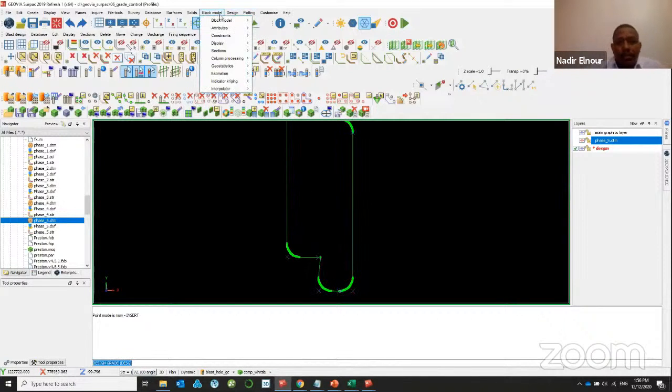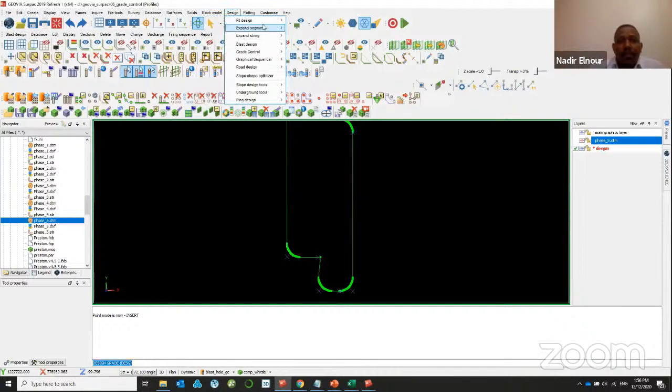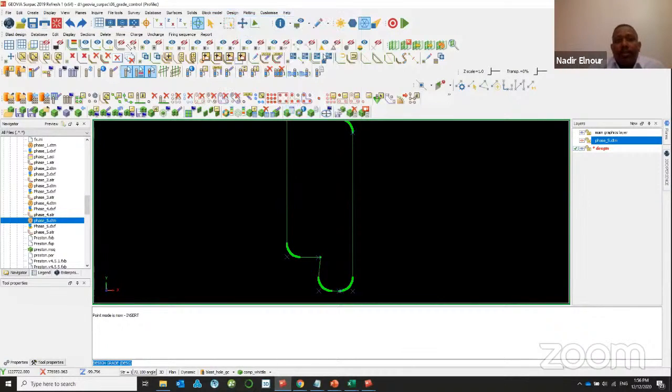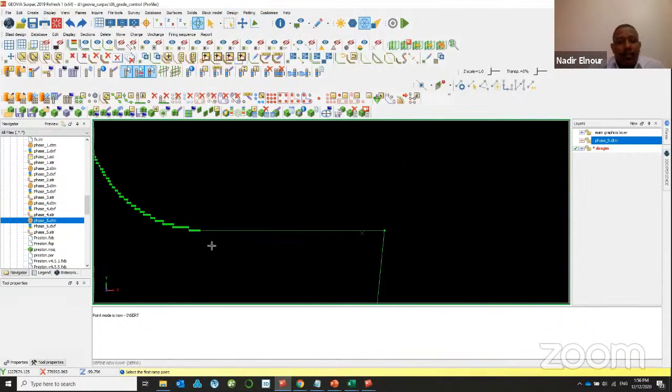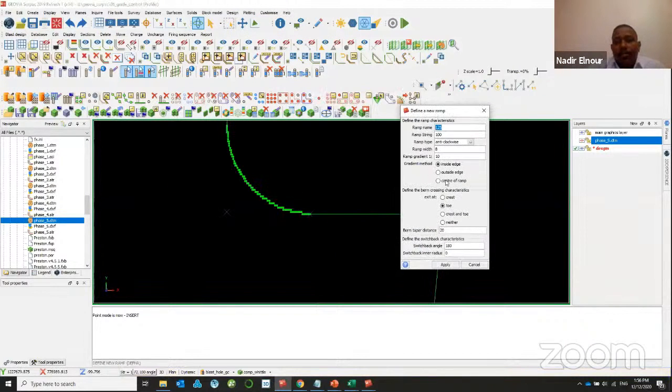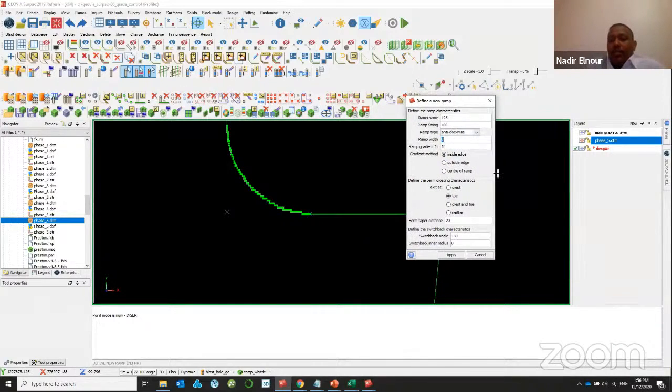The second step is to go and define your ramp. You need to define your ramp, new ramp, and then the ramp requires 2 points. I just need to delete this point because they have problems. So now you need to define your ramp. Automatically you will get the ramp width. Also you will have a minimum design for ramp width based on your loading and hauling plan and this stuff. You just need to design. Now we just keep it as it is.